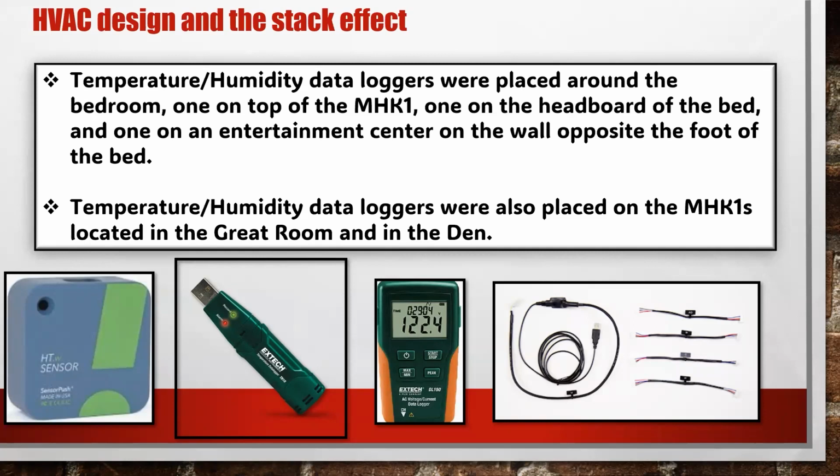Well, here's what I've learned in 9 years of doing this and spending a lot of time looking at the data. You can get away with oversizing a one-to-one system up to 50%. So if you need 12K, 18K is not going to generally cause you problems. But on multi-zones, you can't go over 25% or you're going to have problems. You're going to generate complaints. There's a lot less tolerance for a multi-zone with oversizing, simply because it can't dial down that far.